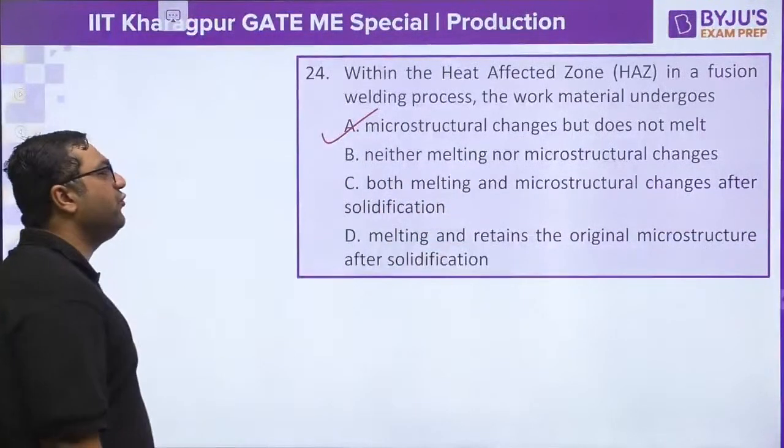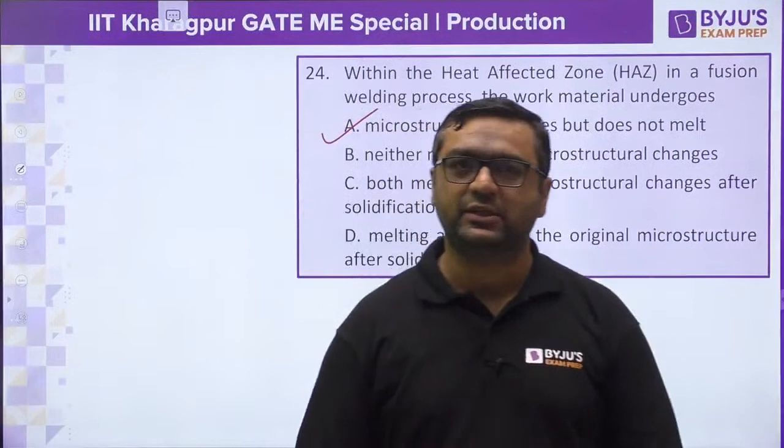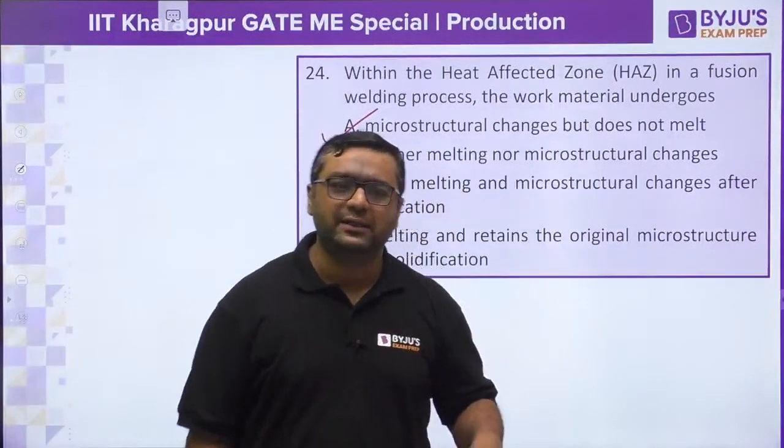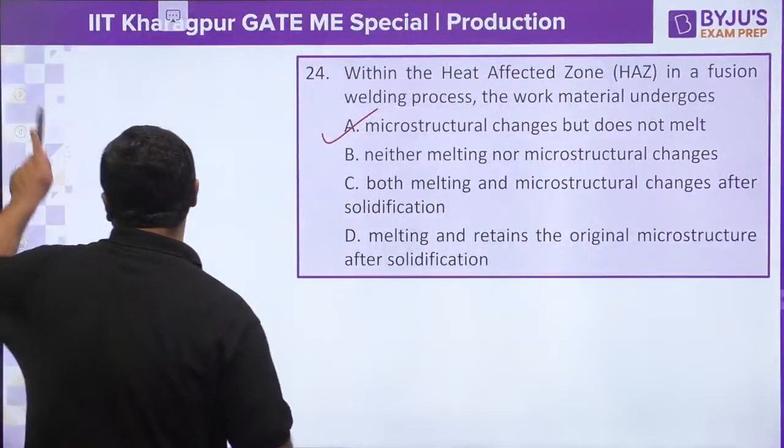Because whenever we are going for the heat affected zone, this is the zone where uncontrolled heat treatment takes place. So because of that, the crystal structure changes there. But my dear, it does not melt. Only microstructural changes happen. So the answer will be A for this.